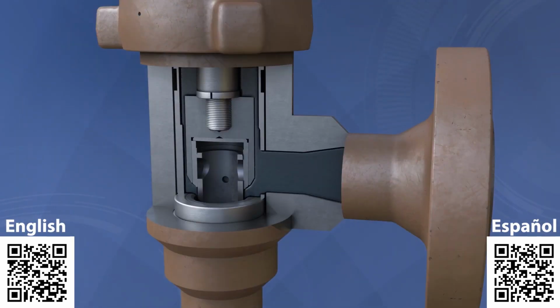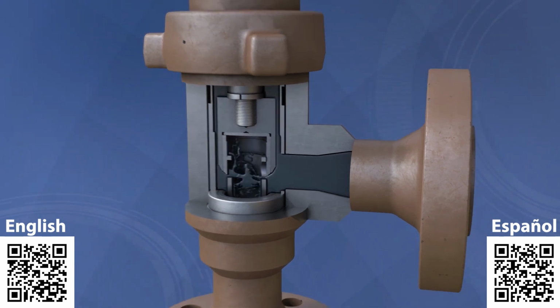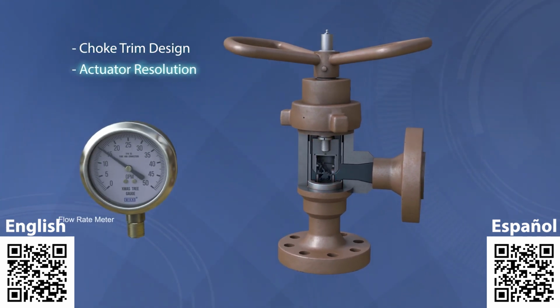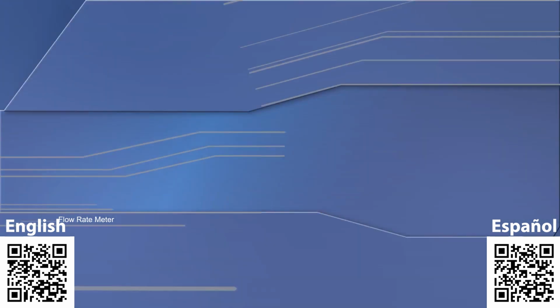The flow rate is controlled by restricting the flow to a small opening or orifice. The degree and level of control depend on three main factors: choke trim design, actuator resolution, and measurement accuracy. Other factors include valve clogging and wear due to erosion and corrosion.